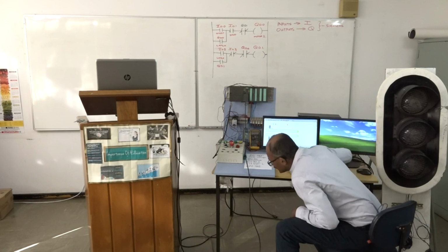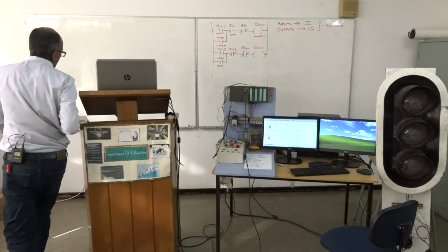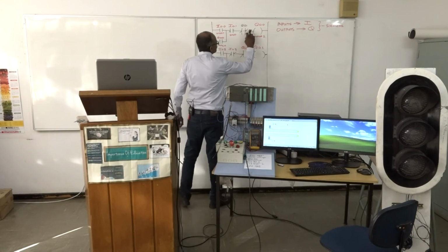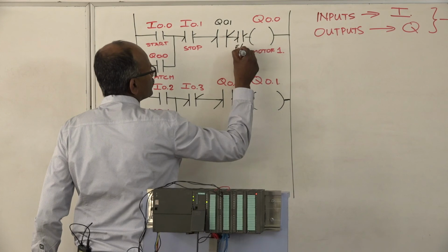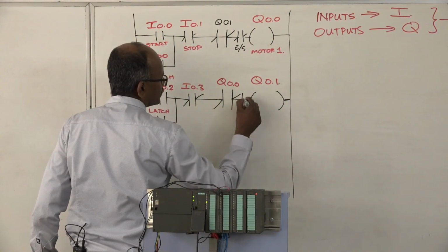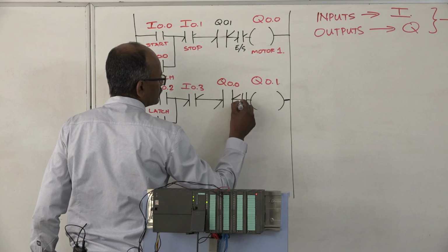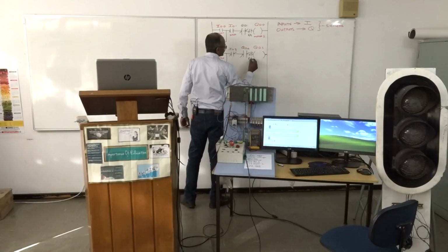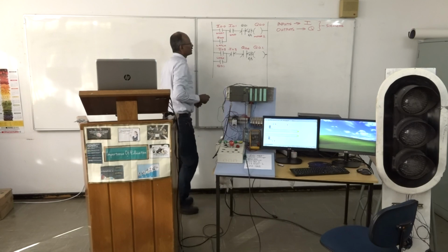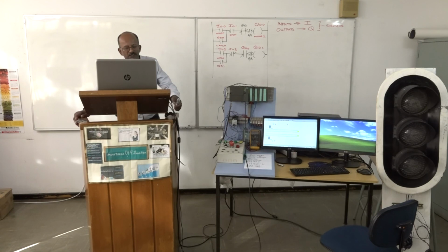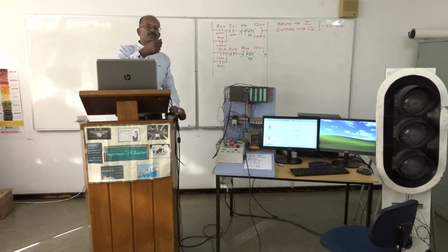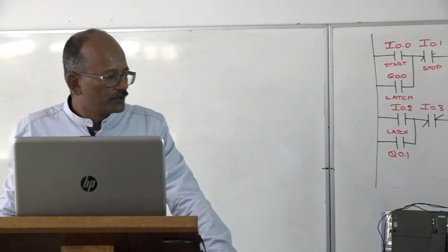So basically, on the circuit itself, all I had to do was put in 2 normally closed switches here and call that your emergency stop, and another one here, and that's your emergency stop. So once those circuits are broken, you'll find you'll never be able to start either of these motors. Sometimes in industry it's a key switch. The supervisor has to come in, turn on the key switch, and then you can actually continue. That's obviously after you found the fault or found the reason for the emergency stop.